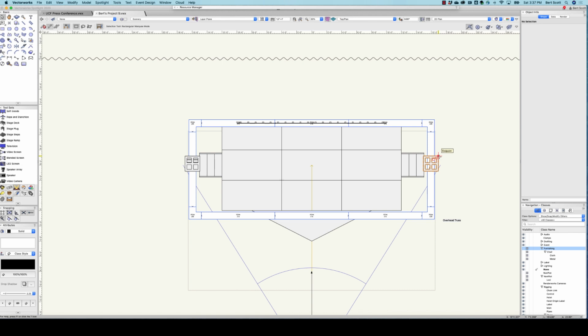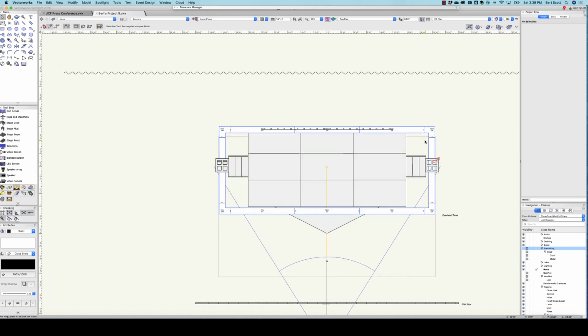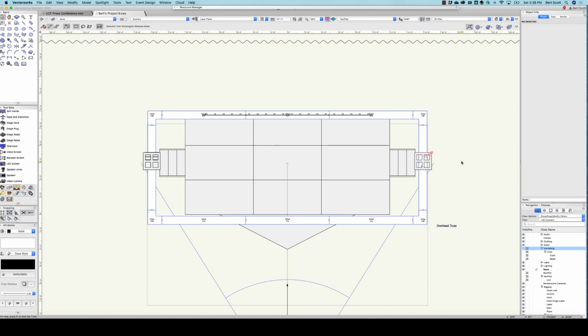It's what's called a reflected plan. It's as if you put a giant mirror on the floor and you're drawing what you see in the reflection. So this pipe is shown underneath the object, even though it's actually on top of the object. And that's mostly just for clarity. That way the pipe is not passing through the object.